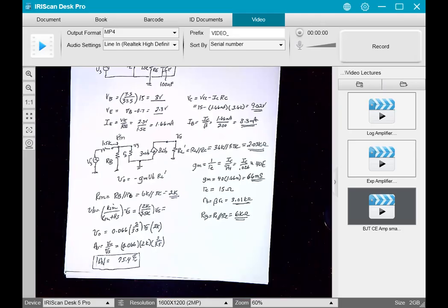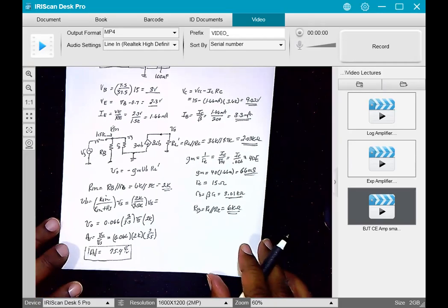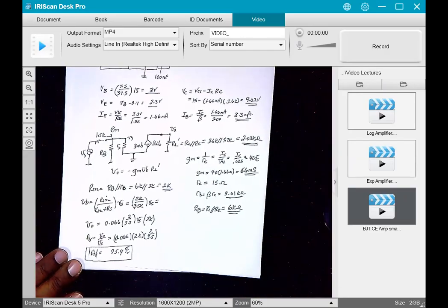So, any question about that? How did you determine what VS was again? I didn't. I didn't tell you what the value of VS was, but I know the ratio of V out over VS is this. So my gain is this. That's a good question, so let's go down that road just a little bit. I didn't tell you what VS was. I just found an expression of V out over VS and defined that as the gain of my circuit.